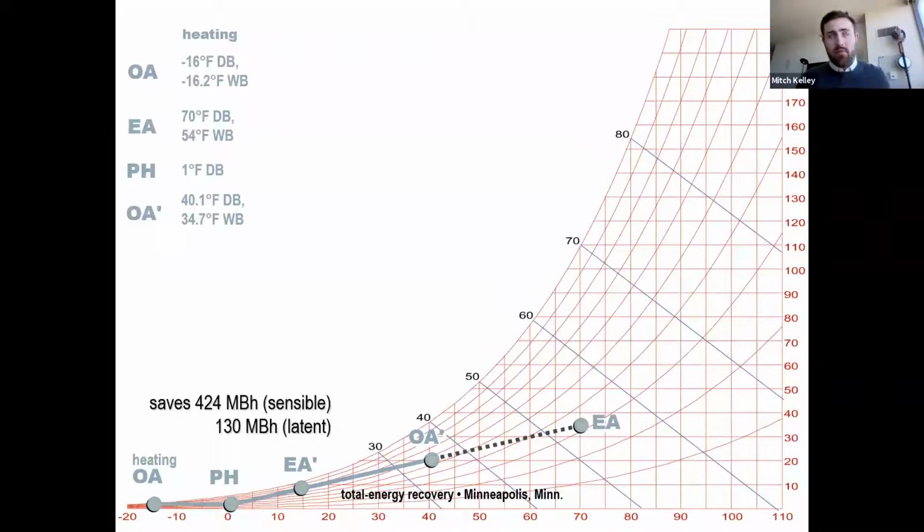And so what is often misunderstood about that is that by using an OA preheat system in these energy recovery applications, you actually allow the wheel to operate during a significantly higher number of hours throughout the year. And the amount of BTUs that you need to put in to get that OA from the entering condition to the frost threshold condition is not bringing that air up to 32. The frost threshold is often maybe 5 degrees.